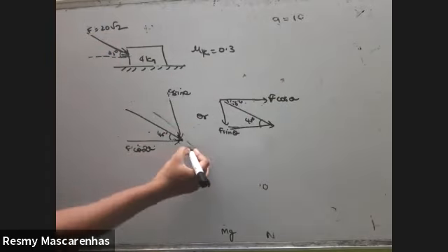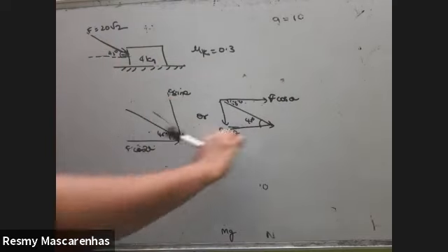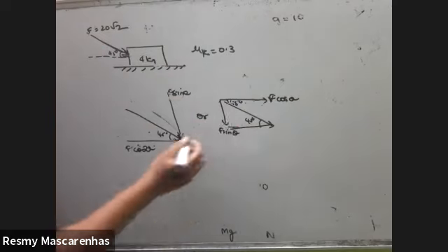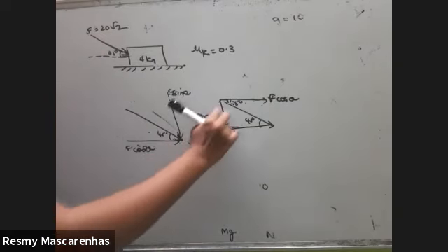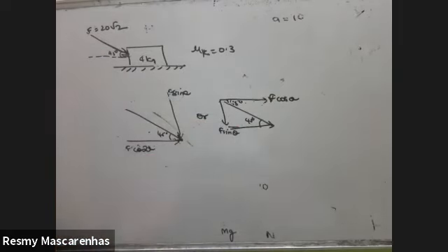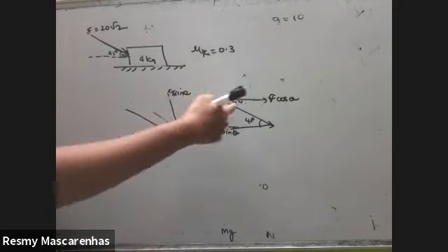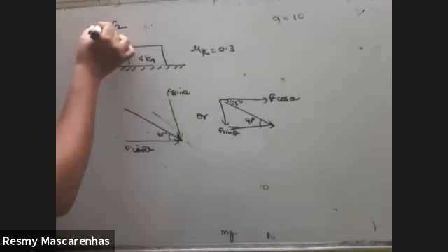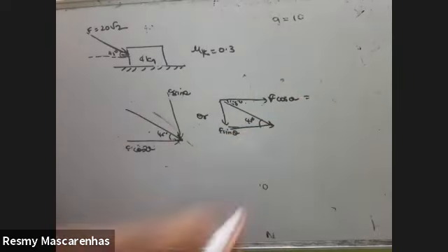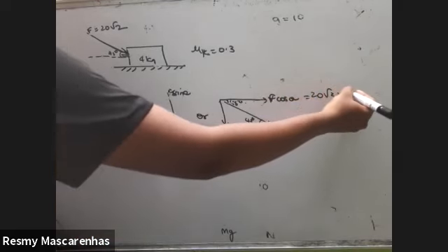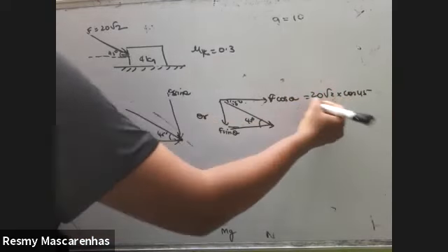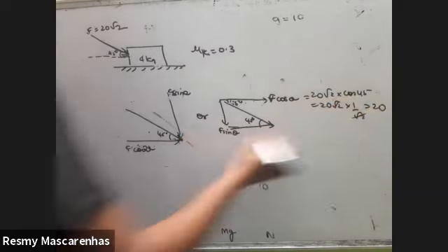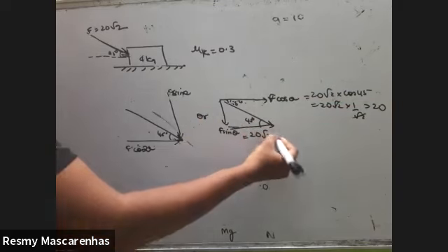So either you calculate from this point or this point, both the ways, the direction. So this is anyways going towards minus y-axis. This is going towards positive x-axis. This one is also going towards positive. This and this is same. So whichever you want to use, no problem. That horizontal component will be 20 root 2 into cos 45. That would be 20. The same would be for your vertical component.